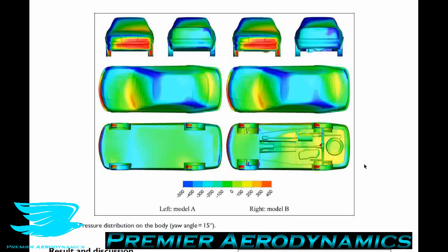The reason is that the bigger the wheel housing is compared to the actual wheel, the more the flow can get in there and move around and hit more walls and increase the drag, typically the pressure drag. If you take this wheel and put it in the wheel housing, it takes up most of the space, so there's not a lot of room for the air to come in, hit around and jostle around and then come out. So that typically reduces the drag by quite a bit.